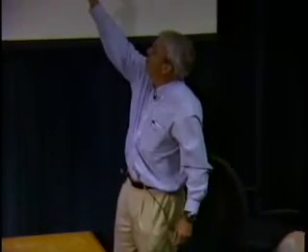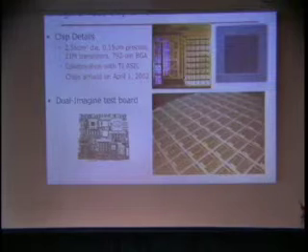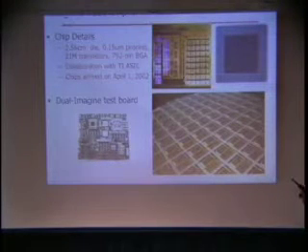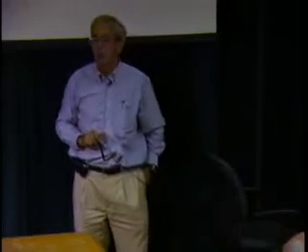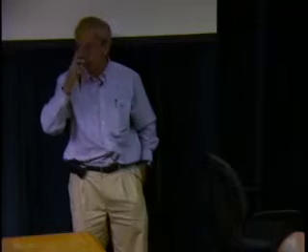So what we chose to do was to develop a machine that could expose parallelism and locality, but do it in a programmable way. Imagine, I don't have block diagrams up here, but you can see almost from the chip floor plan up there that there are 8 arithmetic clusters. Those are 8 things vertically. In every arithmetic cluster, there are 6 32-bit floating point units. So there are 48 floating point units in Imagine. In each cluster, there's 3 floating point adders, 2 floating point multipliers, and 1 floating point divide square root unit.